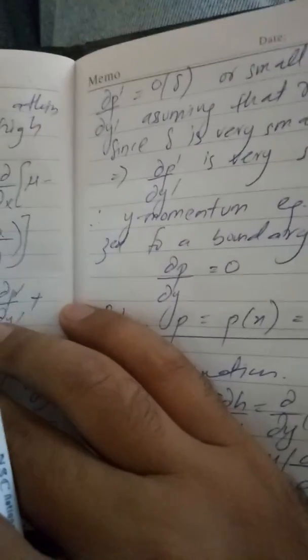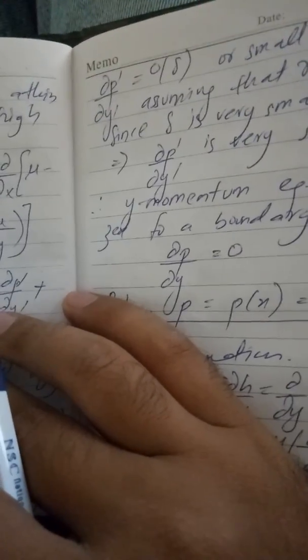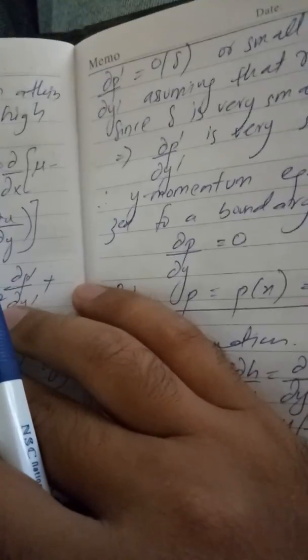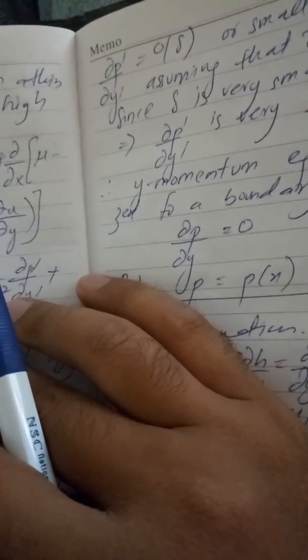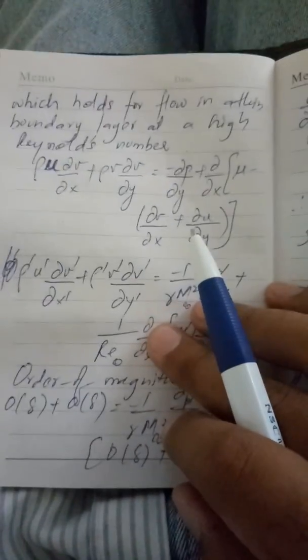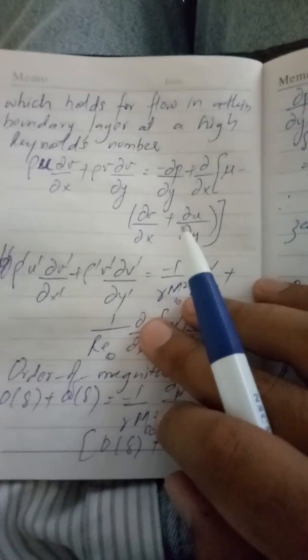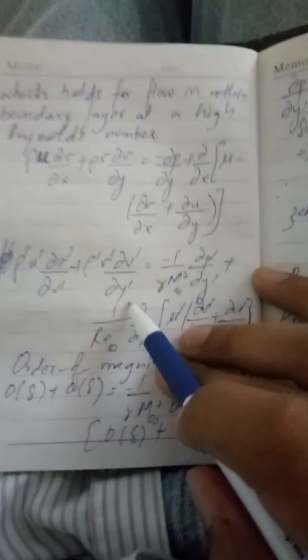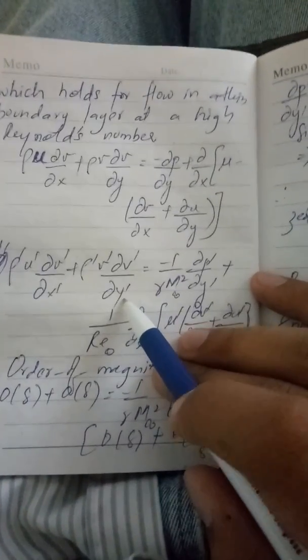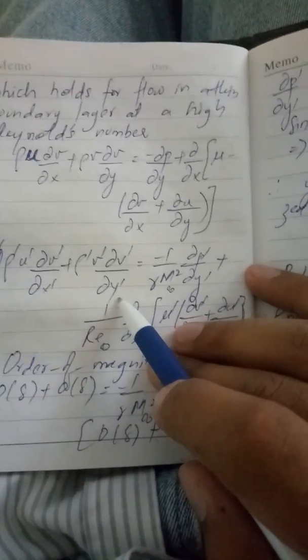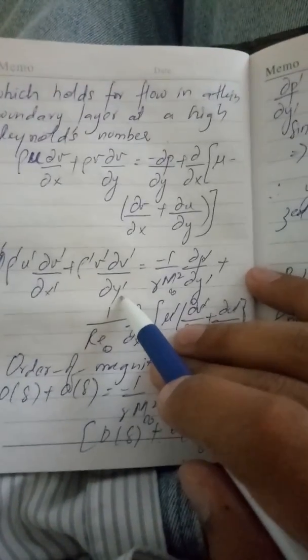Again, coming back to that same order of lambda equation, we have come across that in terms of y momentum. The x momentum was just coming from order of 1 back to order of 0, and there we got the x momentum. And in y momentum we have used order of 0, and we have moved towards order of 1, but in terms of v prime, not in terms of u prime, and that is the difference.